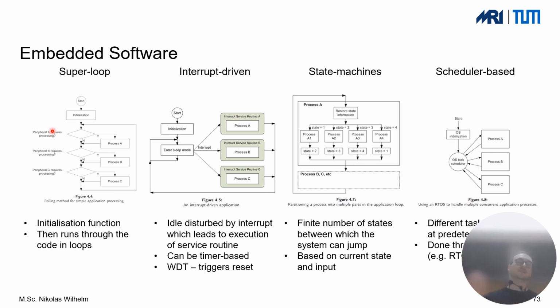And once everything is done, you just run your main loop where you have some kind of main logic. So for example, read all the sensor signals at the start, and then perform some kind of logic, some kind of calculation, and then, for example, put the respective power on the motor. So we're going to set the PWM signal of the servo motor to a respective value. But of course, depending on your application, there can be different solutions in doing so.